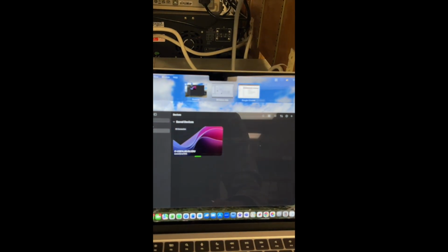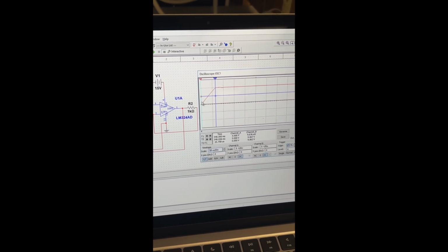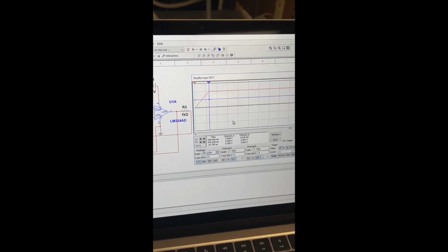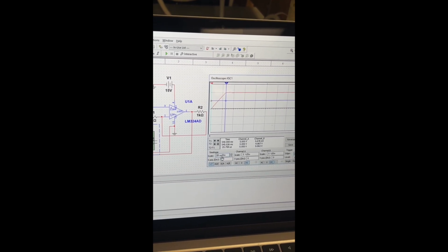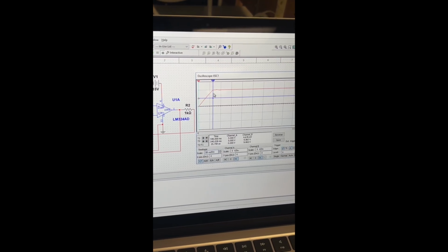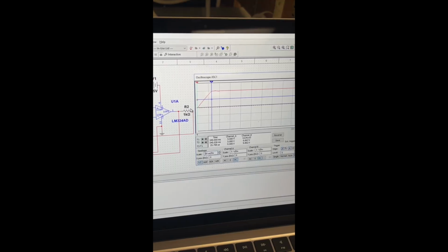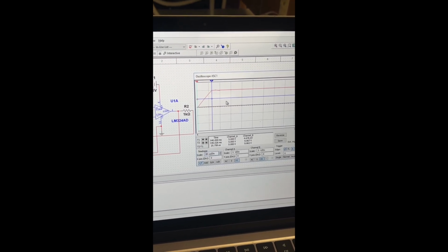And I've also done the simulation here. So as we can see, the blue line is the input. So it's like a perfect square wave. It just goes up to 5 and goes that way, and I've zoomed in quite a bit, or changed the scale to 20 microseconds per division. And then the output, we can see the delta V does go higher. It goes to about 10 volts instead of the input being 5.